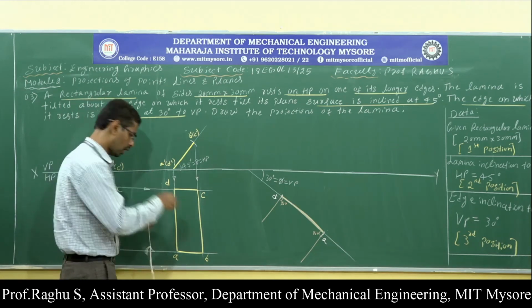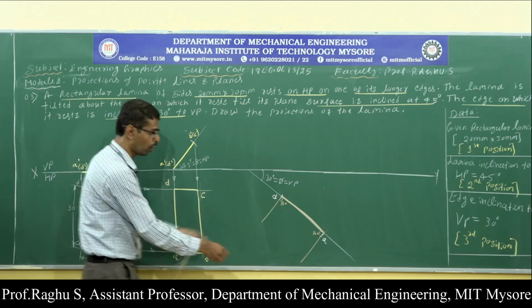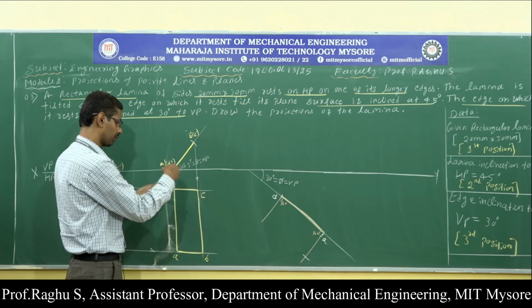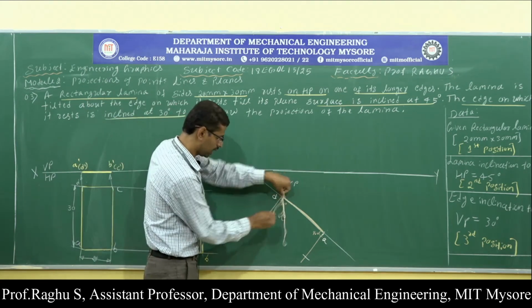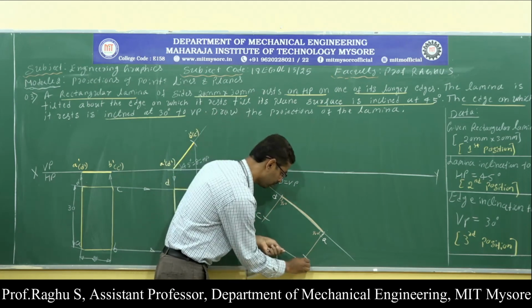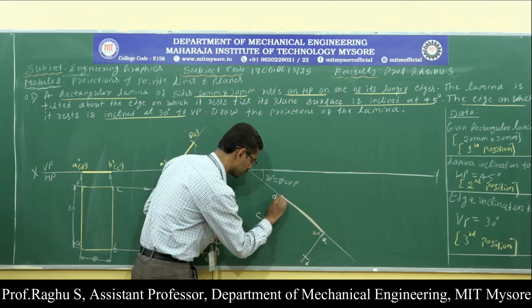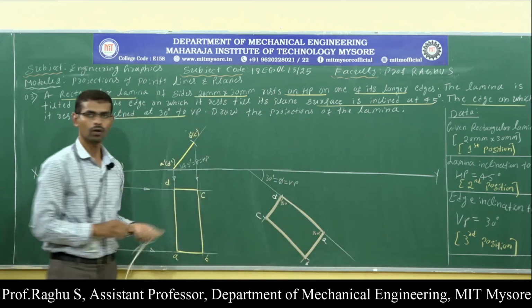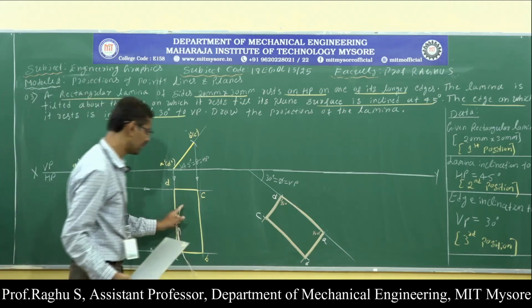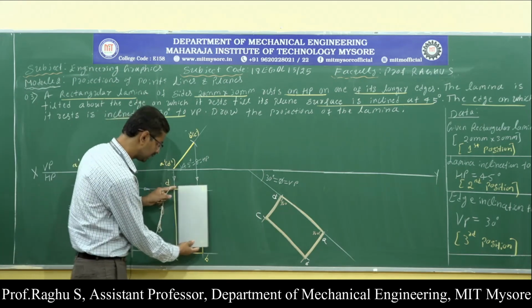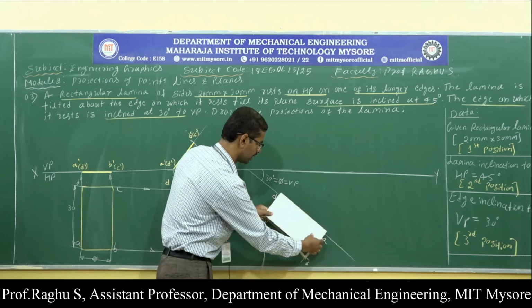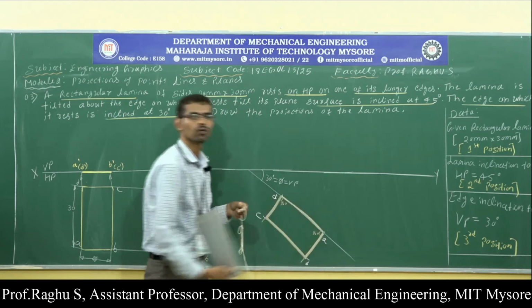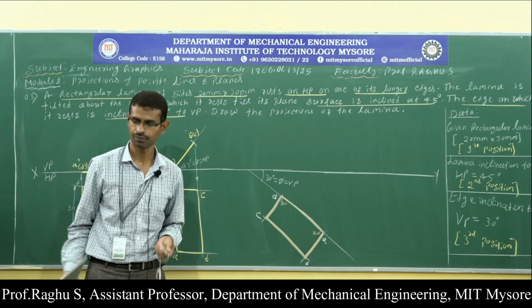Measure the distance from A to B. I know the position of point A, right? Cut an arc. Measure the distance from D to C. I know the position of point D. Cut an arc. Here you will get the points C and B. Now connect these two points. Just I have redrawn this lamina by placing the resting edge like this or like this. Here I have placed the resting side on the VP inclination line.